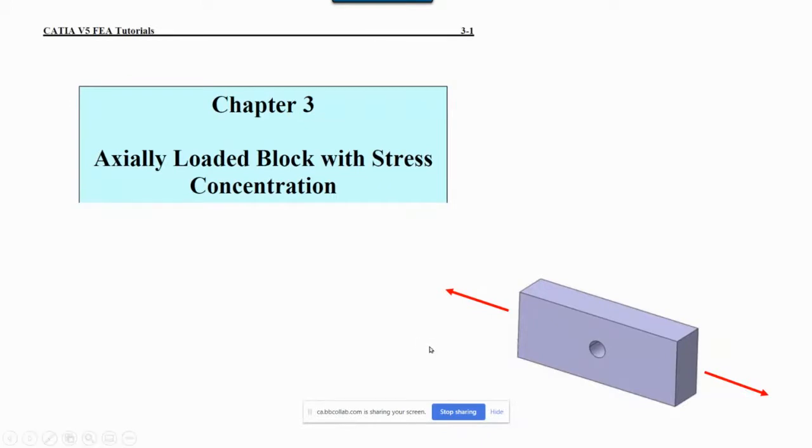Correct, correct. And this is what we call a stress concentration. Because think about it like this. We have a force, and that force was acting on a big cross-section here. But when it reaches its effect, in the middle, the area has decreased. And if the area is decreased, the stress is going to go up. Because force is constant, area has decreased, the stress is going to go up. And it turns out that the top and the bottom, not the sides, the top and the bottom carry the most tensile stress, and that is what is called stress concentration. That hole or notch is leading to a stress concentration.